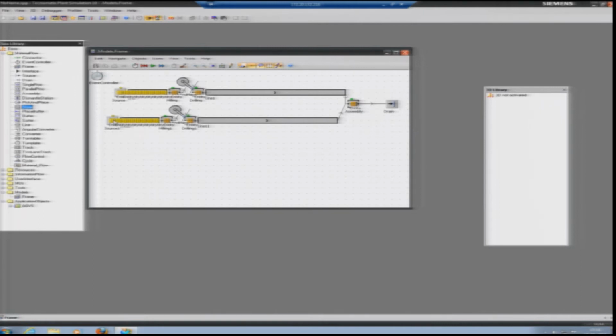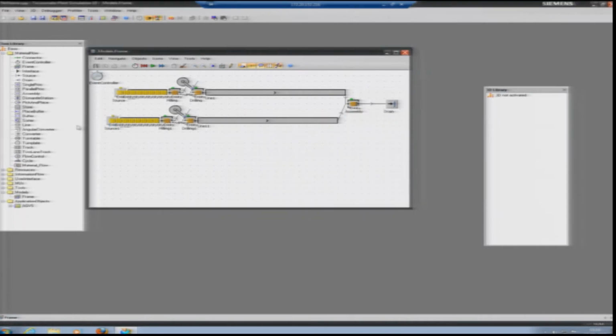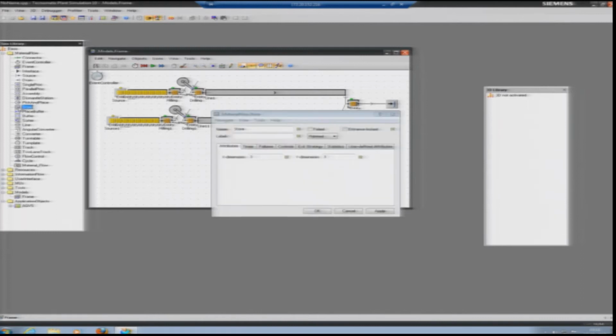These mobile units are these yellow entities. This is MU. By MU we mean mobile unit entity, this one is telling this. So these mobile units are stored or can be stored using this store, and one can define the size of the store by specifying the x and y axes. For example, a total of 9 pieces can be stored, 3 into 3, total 9 pieces. This is the default entry.